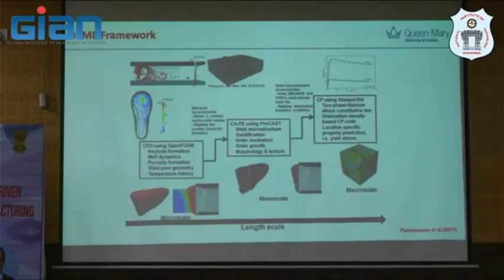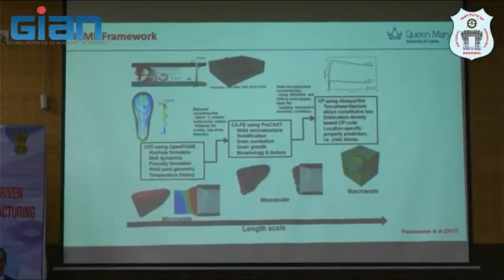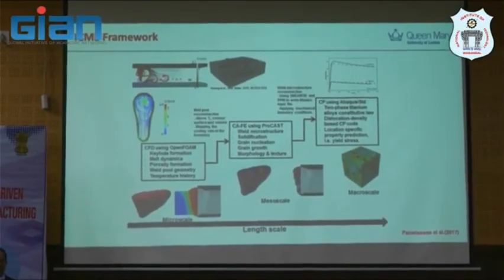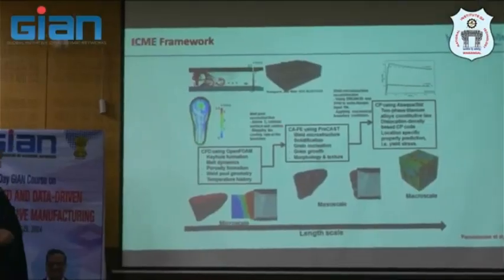And after that, we link this microstructure reconstruction, again using, at that time, I think about 2014-15, Dream 3D, which is more robust now, for the 3D microstructure reconstruction. If you do a lot of EBSD serial measurement, you may use Dream 3D to reconstruct your microstructure for finite element calculation as well.